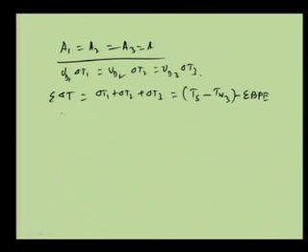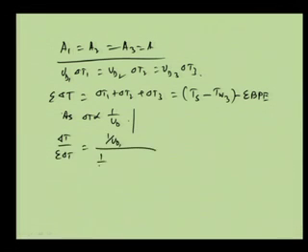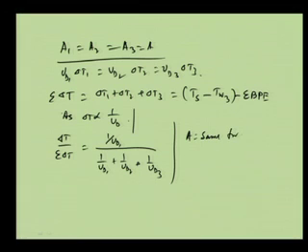So, as delta T is proportional to 1 by UD, we can calculate the delta T values. Delta T by summation of delta T is equal to 1 by UD1 divided by 1 by UD1 plus 1 by UD2 plus 1 by UD3, provided the area is the same for all effects.